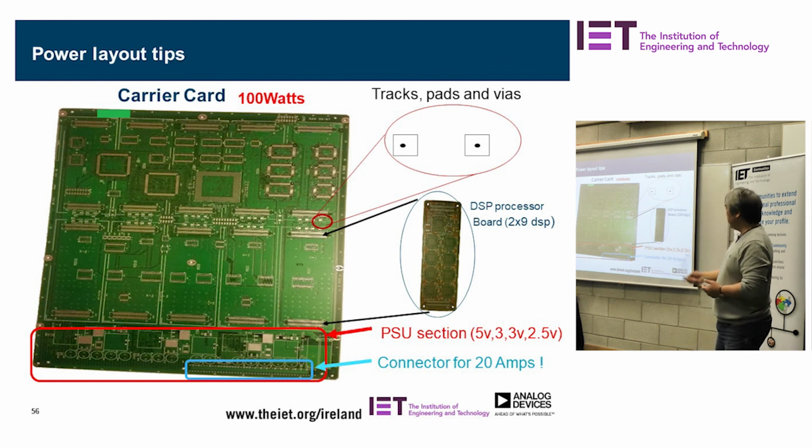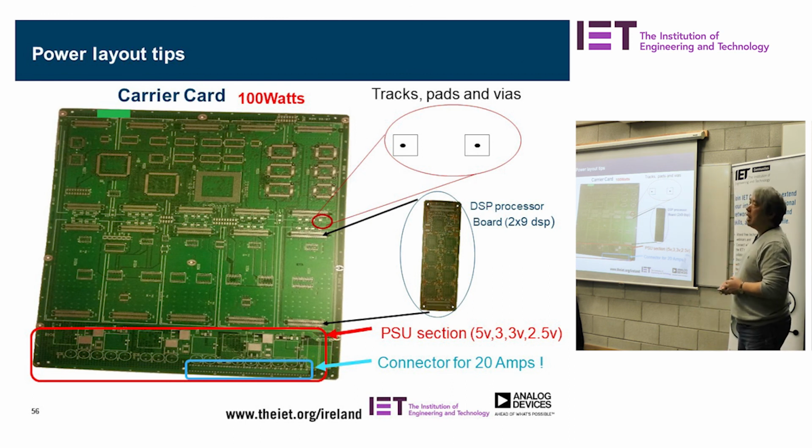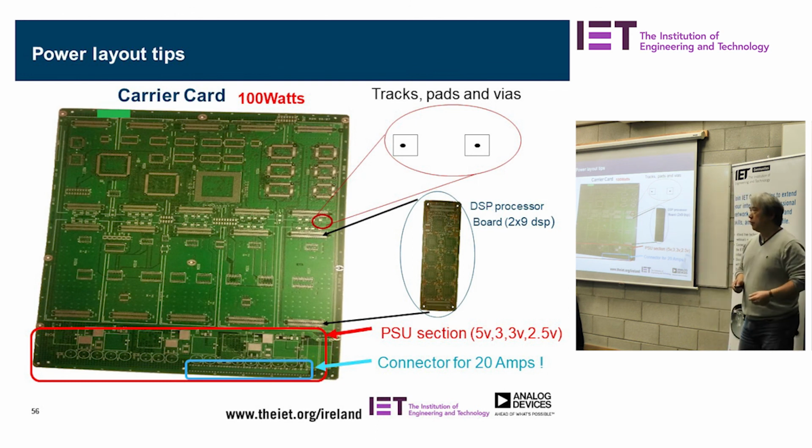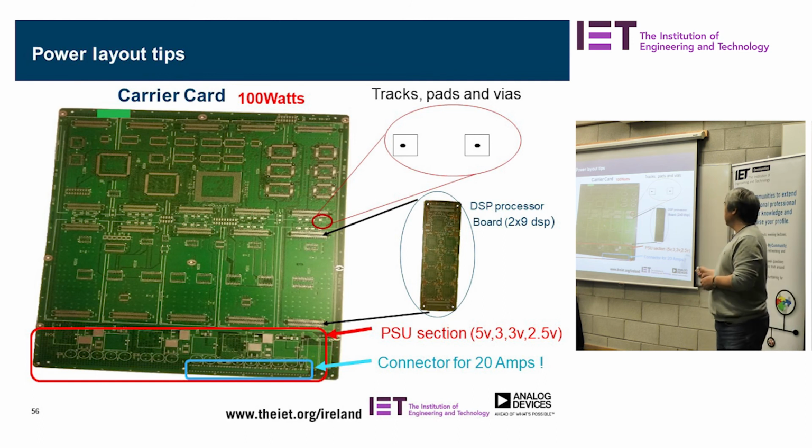And then the next thing is, because it's such high power, there are fuses, and the board has to be fused adequately to avoid pulling the whole thing down. The board takes about 2 amps, maybe 1 to 1.5 amps drawn at full power, so we fuse it with a 3 amp fuse. What happened was he did the pads with 1 via to 1 pad.